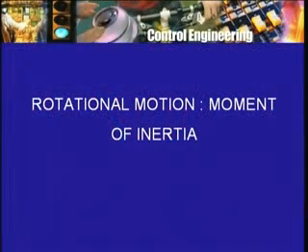You could think of even a flywheel at the one end of the shaft. So what I am implying is that there is a rotational motion of not only the shaft but also the armature, the load, and therefore one has to consider the moment of inertia of this rotating part.